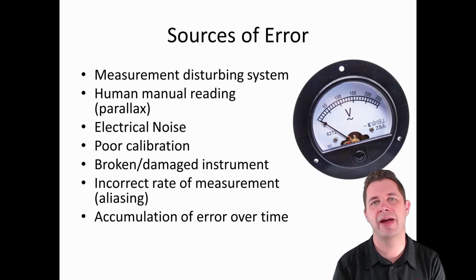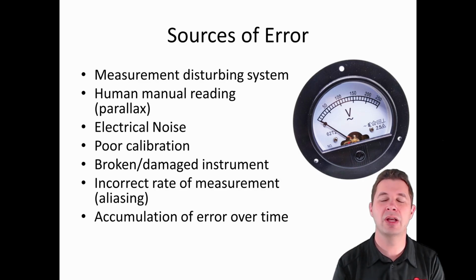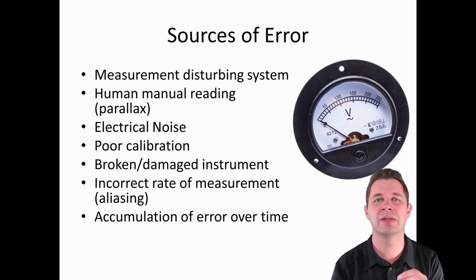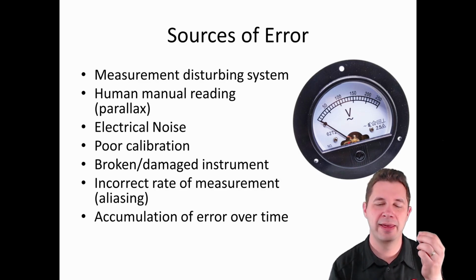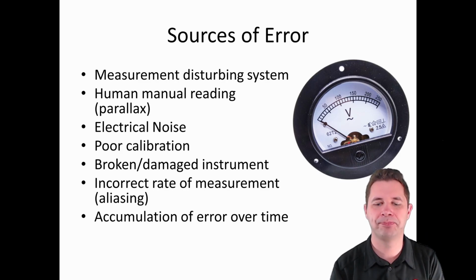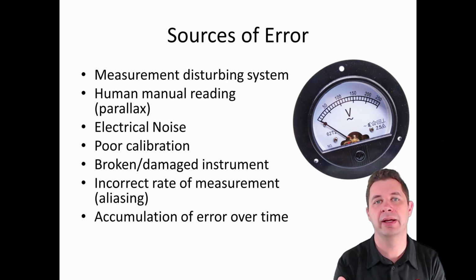Some of those sources of error, particularly when we're thinking not just about the operator reading things but also the actual measurement itself, come from the error we introduce when we're actually performing a measurement. Some of our sensors are what we call self-heating, which means as we perform our measurement, the sensor warms up over time, which will of course disturb the operating environment we're within.